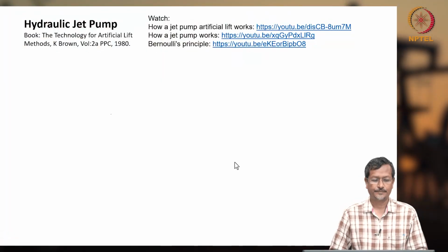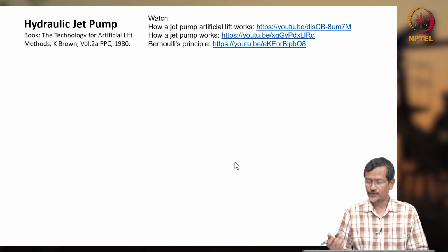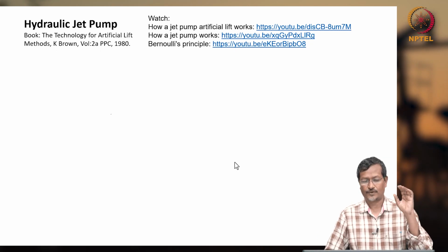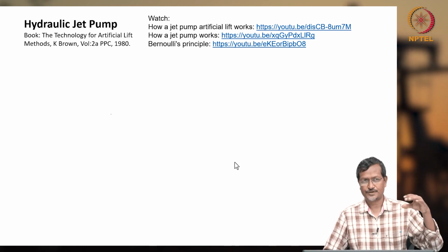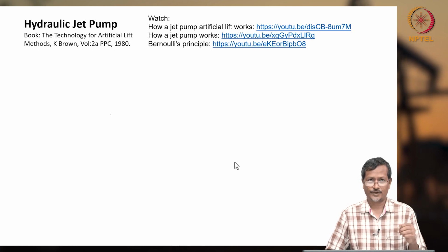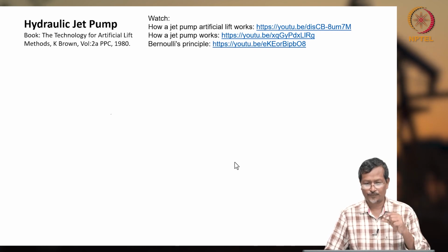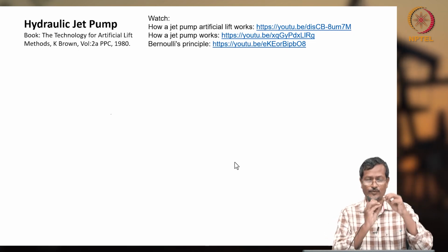Good morning, everybody. Today I'll be teaching the hydraulic jet pump. In a hydraulic jet pump, we have one nozzle, a diffuser, and a mixing chamber. Then we are trying to create low pressure, and that low pressure will be sucking the wellbore fluid.